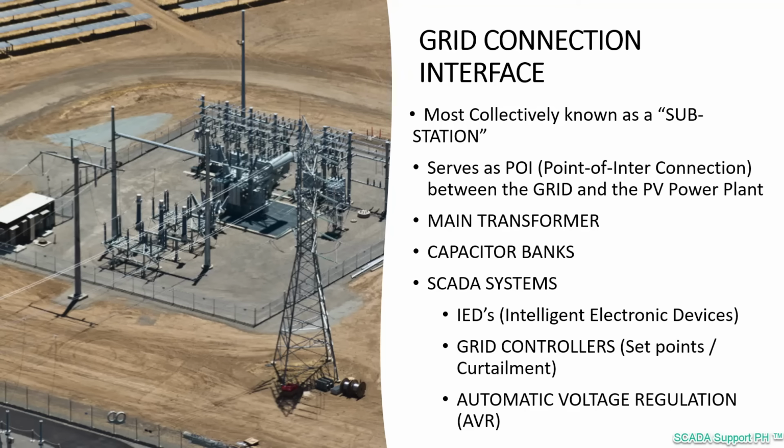When we talk about step-up transformers, the output from the inverters generally requires a further step up in voltage to reach the AC grid voltage levels. The step-up transformer takes the output from the inverters to the required grid voltage, like for example 25 kV, 33, 38, or even 110 kV, depending on the grid connection point and country standards.